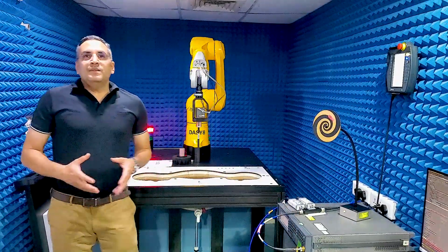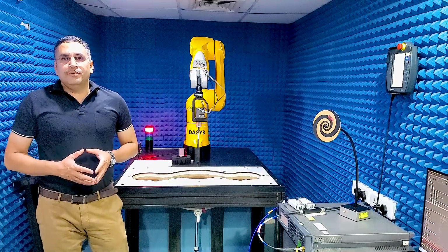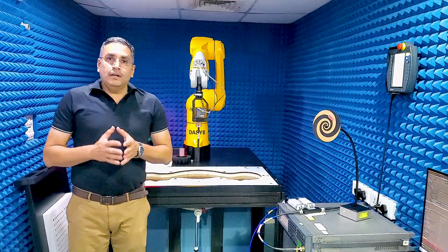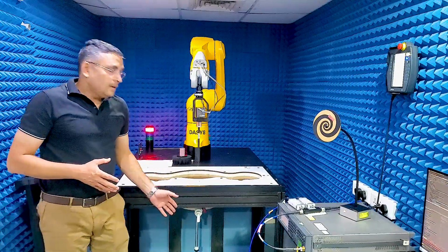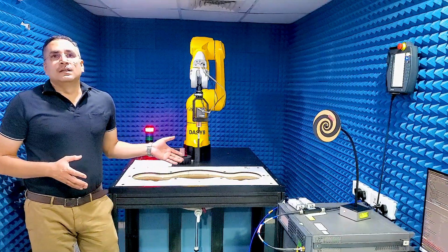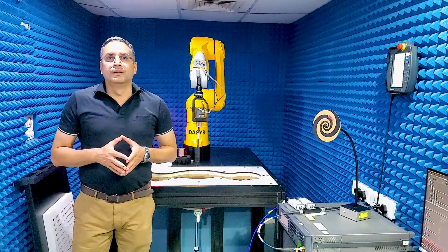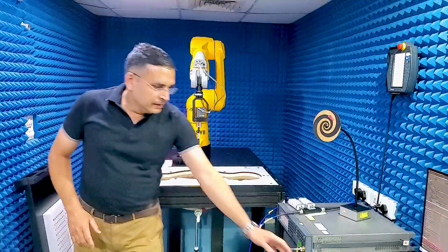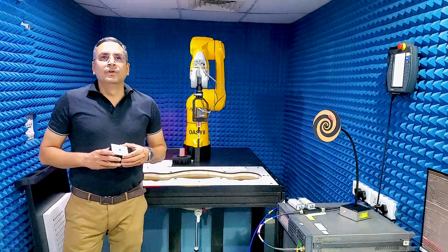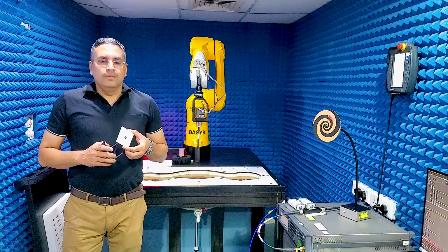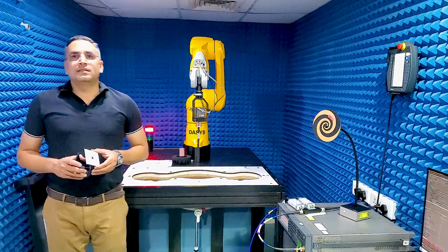The new DASY8 module SAR V16.2 offers small but important new improvements. It makes SAR and APD testing up to 10 GHz easier and even more accurate. I particularly liked this new patch antenna, which I will definitely use for system verification before testing compliance of any Wi-Fi 6E devices in the future.